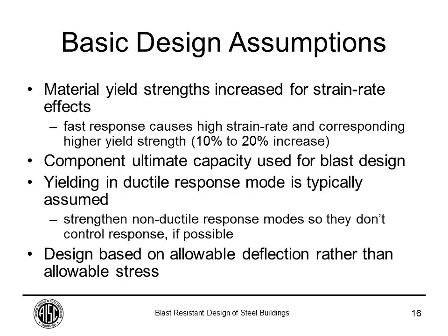Next, you want to know that we work in the ultimate capacity region. So you can picture a beam with both ends fixed. In typical conventional design, you have to limit the capacity of that beam to the first yield that happens at the supports. When we're doing blast loads, we push components to the ultimate capacity. So if you have a fixed beam, you're going to yield at the ends, but you still have capacity until you finally reach the collapse mechanism when the hinge forms at midspan. So you're going to have material increases, and we're going to go to ultimate capacity.